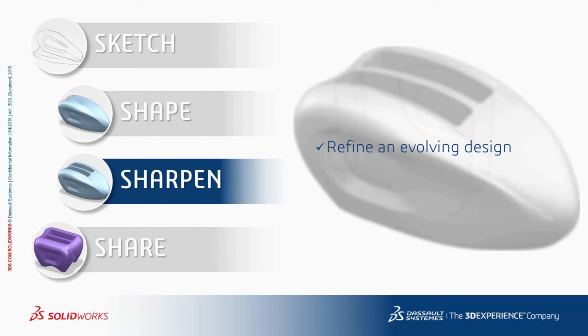Sketching right on the solid model, not to maybe turn it into a feature like Brad did with the button, but just to sketch on the solid model during a project review meeting and say, hey, maybe we take some material off over here, or if we added the control panel in this area. Really amazing benefits to being able to sketch right on the solid model, as well as taking parametric features that we all know within a 3D CAD system, like cuts and chamfers and fillets and draft and shell, and applying that to our sub D solid body that he created in the initial step.